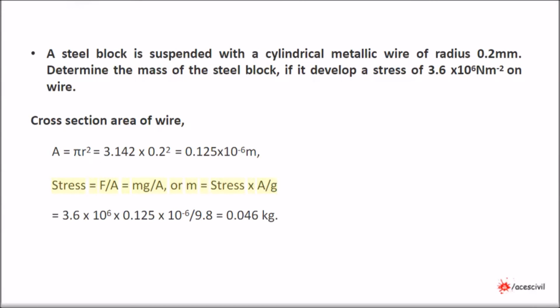Stress equals F/A equals mg/A, or m equals stress x A/g, equals 3.6 x 10^6 x 0.125 x 10^-6 / 9.8 equals 0.046 kg.